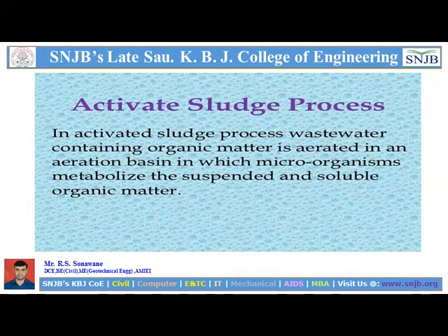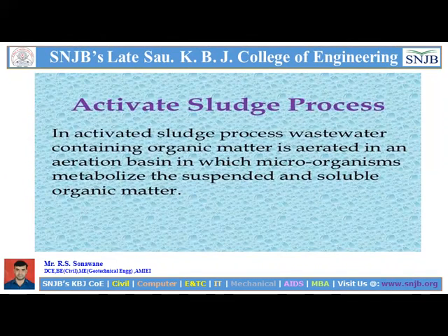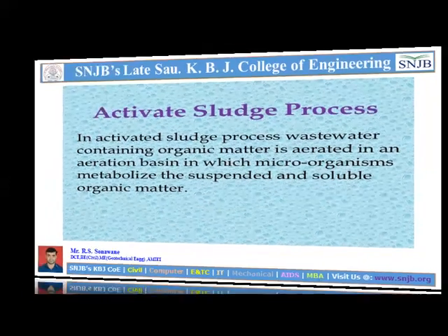So you know that in the activated sludge process, the wastewater containing organic matter is aerated, and that organic matter mixes with the oxygen in the aeration basin, in which microorganisms metabolize, that means utilize, the oxygen through that aeration chamber, and are able to degrade the organic matter, suspended matter or soluble matter. This is about the activated sludge process.